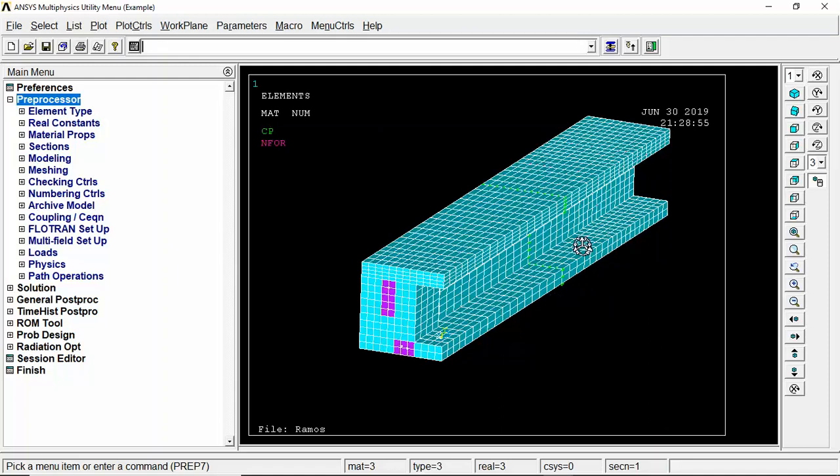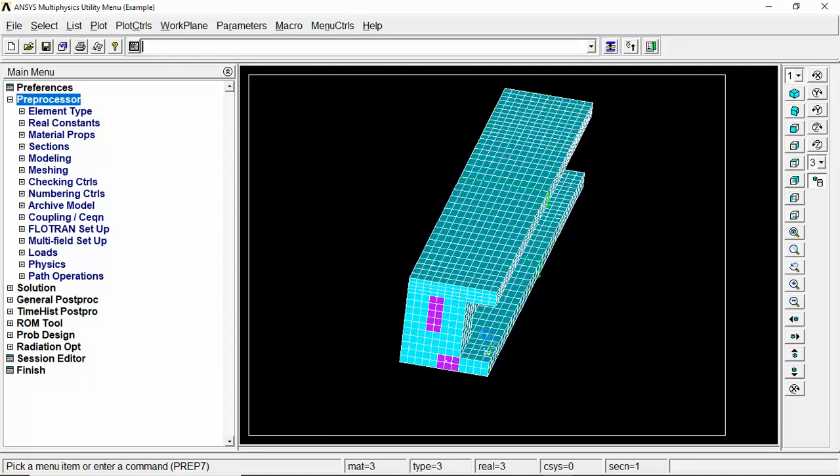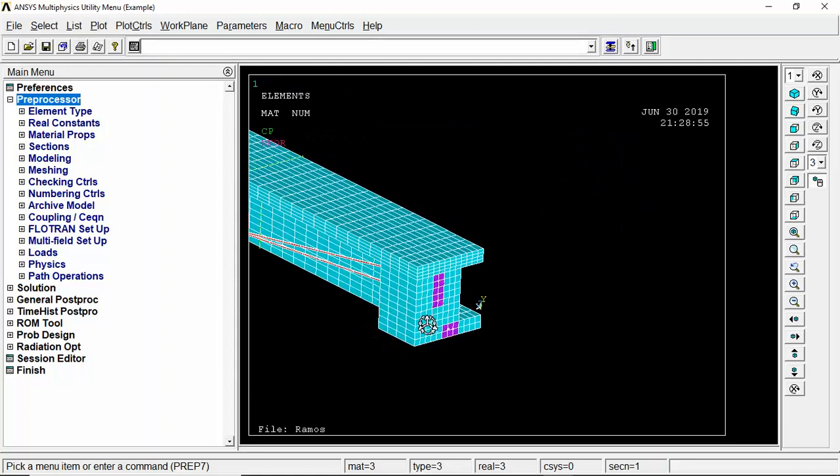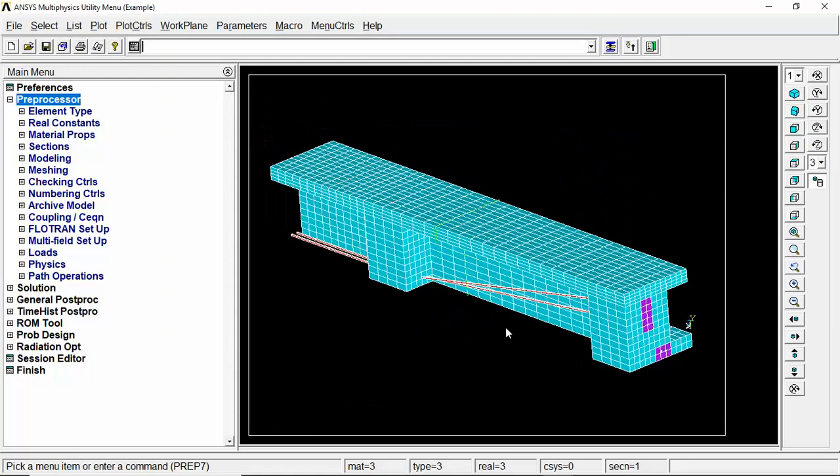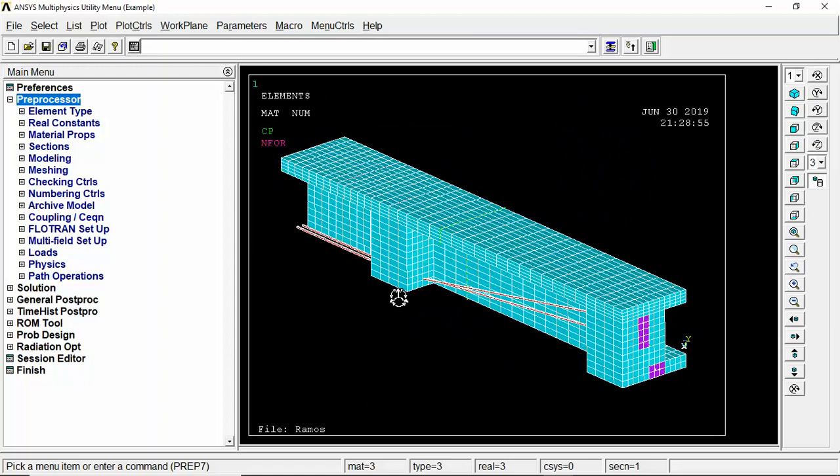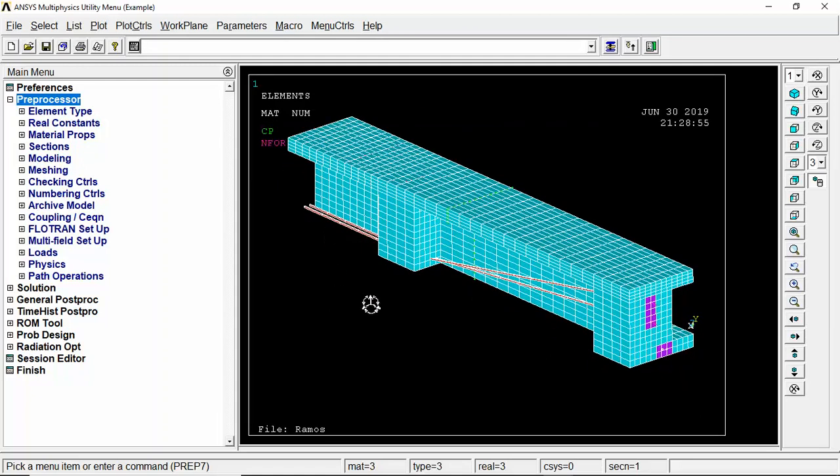For example, in this part I may have greater stress than in these parts, but in these two unbonded and external tendons the story is different, and the stress only changes at the positions where I have a deviation in the path of my tendon.